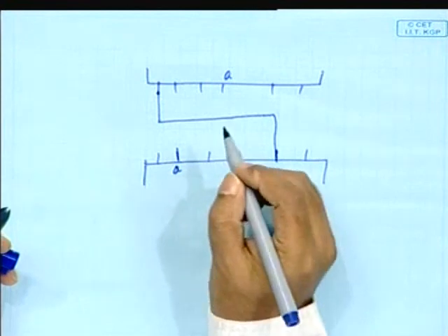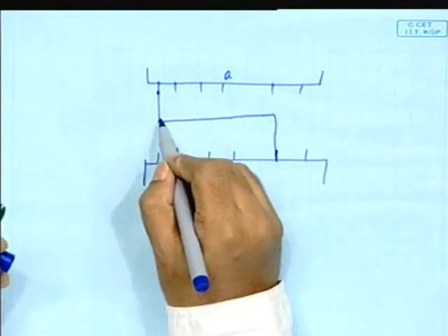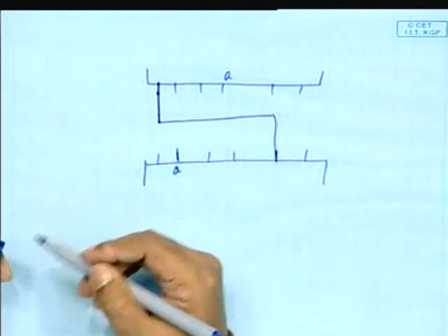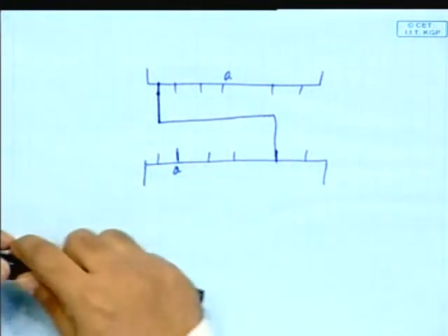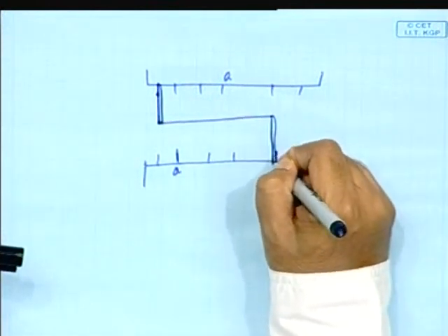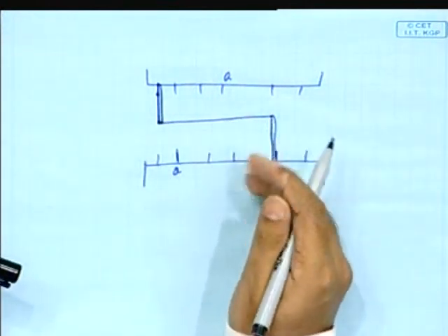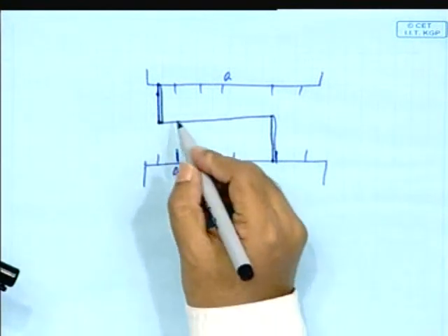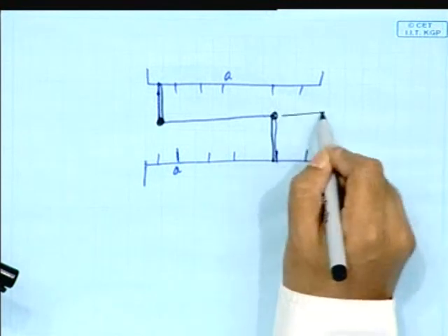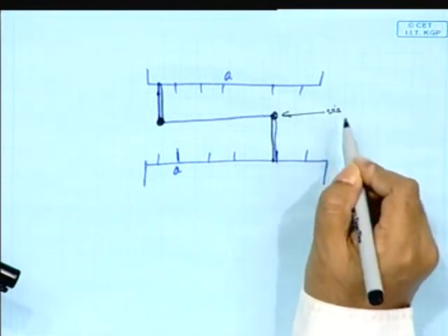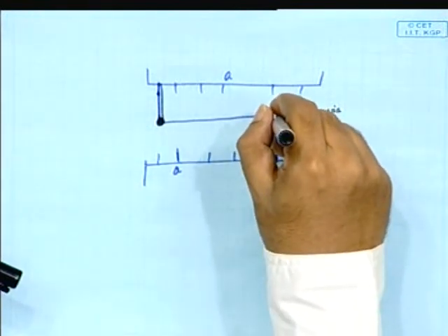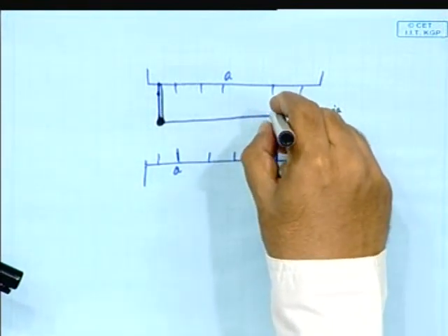So what happens there in two layer routing is that the ones which are vertical are in one layer of the chip, and the horizontal one is in another layer of the chip, and there is a via, which is a connection which goes from one layer of the chip into the other layer of the chip.